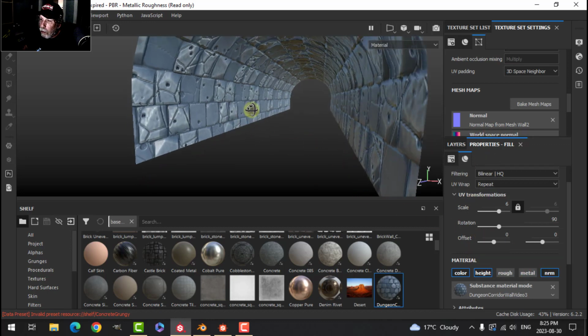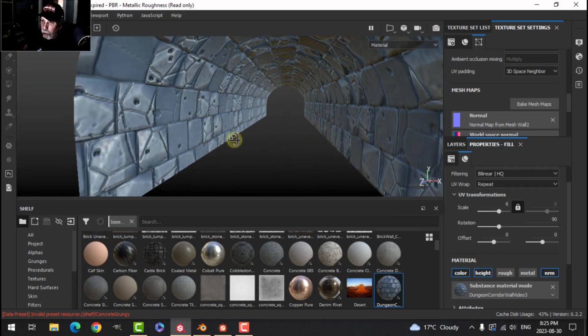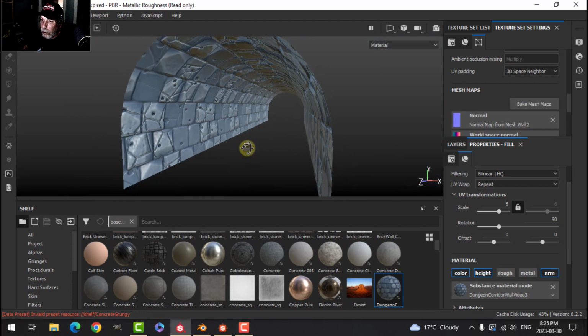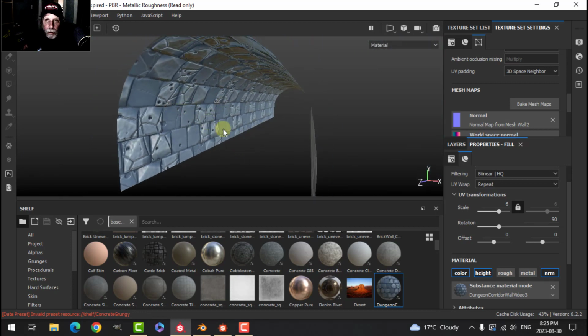And what we want to do next, though, is actually get these bricks to look like they're pushing out, because it's flat. And then I'll change the resolution. We can have a look at that. And we'll change the HDRI image so we can see it in different lightings. And then we'll export it from here, and we'll have a look in Blender.